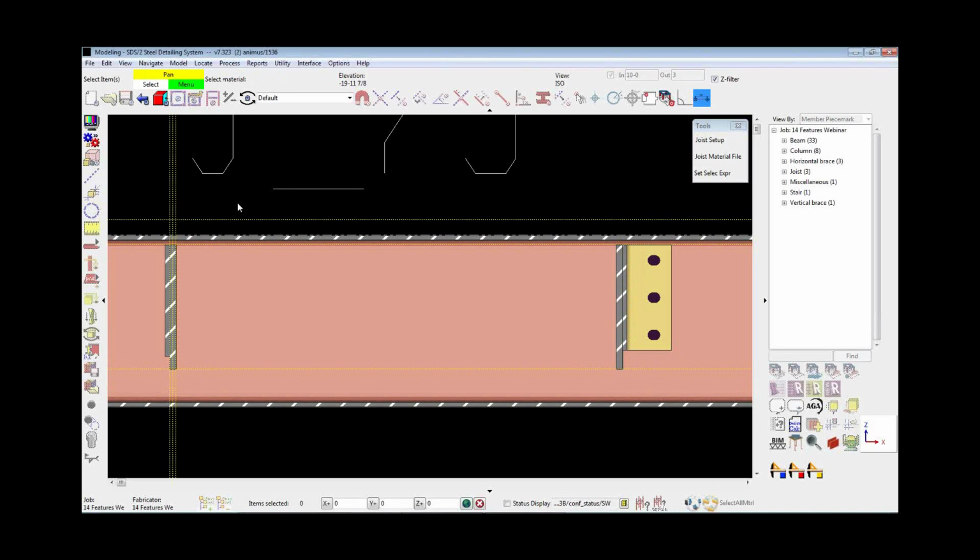It kind of breaks a link to them and won't necessarily erase them, but it'll re-add them before you can erase them again. So again, just to show that, I'll hit construction line add material. I pick my stringer, it adds those. If I want to erase them, I use that same command, and it gets rid of those.